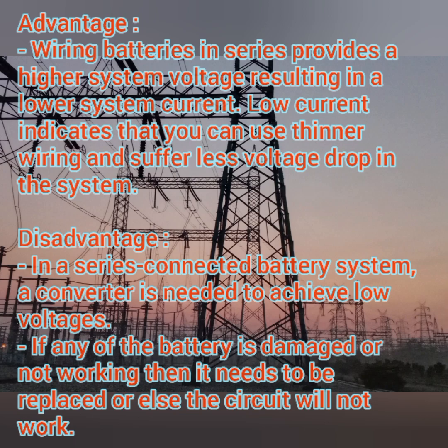Then the main disadvantages: if we connect a battery system in series, a converter is required to achieve a lower voltage, because we can easily achieve a higher voltage when connecting in series, but in order to bring this higher level voltage to a lower level voltage, we need a converter or a charger kind of thing.